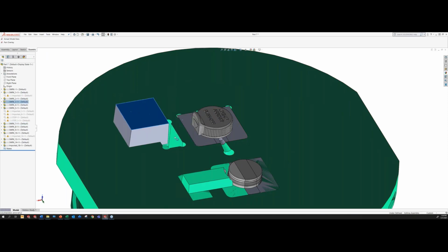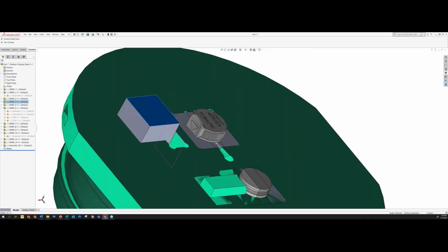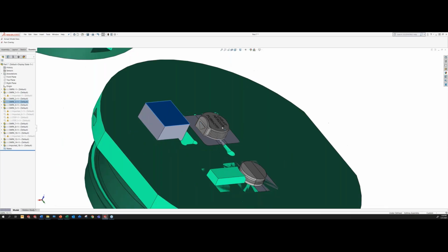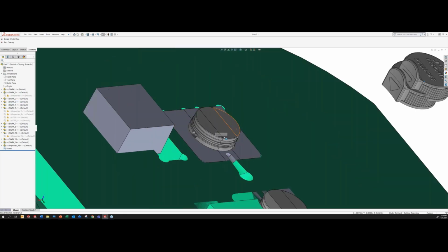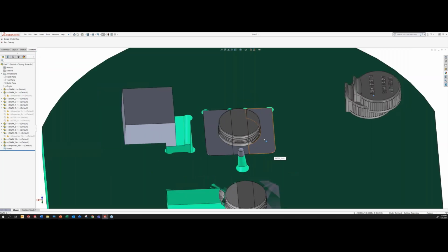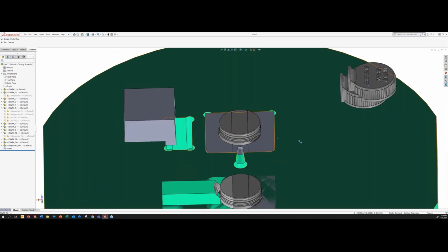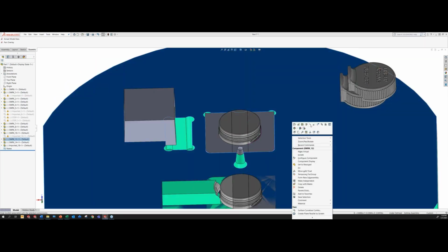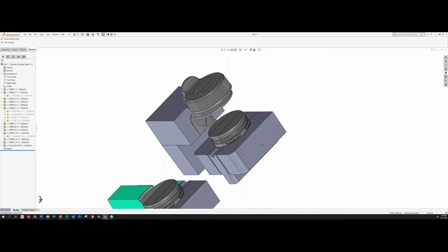So we've got this loose piece here that's creating the outside arrow. And if I just pull this part out of here, we can start to see we've got 3 internal hand loads. So we've got 2 split lines that are actually going to be on the inside of the part. So when the part ejects, all 3 of these hand loads will come out at once. Let me hide this so you can kind of see.